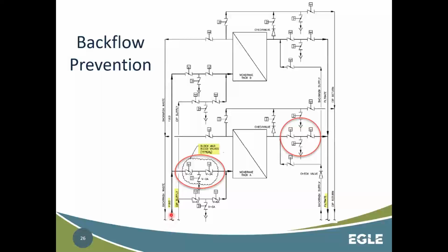This bold line is your normal water coming in, into membrane rack B and rack A. Normally the water goes through here, comes out, and then here's your filtered water. But you'll see we also have a CIP, clean in place chemical solution line that comes in and ties in here. So right here, we have a direct connection between potentially nasty chemicals and our water.